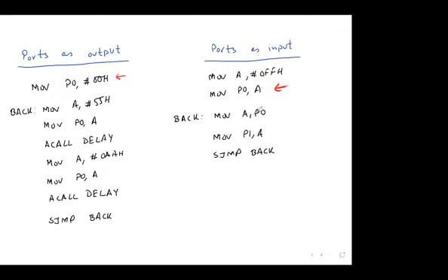Try to see that your port 0 is an 8-bit port. So definitely it will send you 8-bit data or 1 byte size data. And your register A is also byte size or 8-bit size. So the size is exactly the same, so there will be no problem with that. Then after getting the information from the port, what you do is totally dependent on the designer or your problem at hand. In this particular example, we are reading the data from port 0 and we are sending the exact same data to port 1. And then we jump back and we keep doing this indefinitely. Is it understood now? Yes, sir.